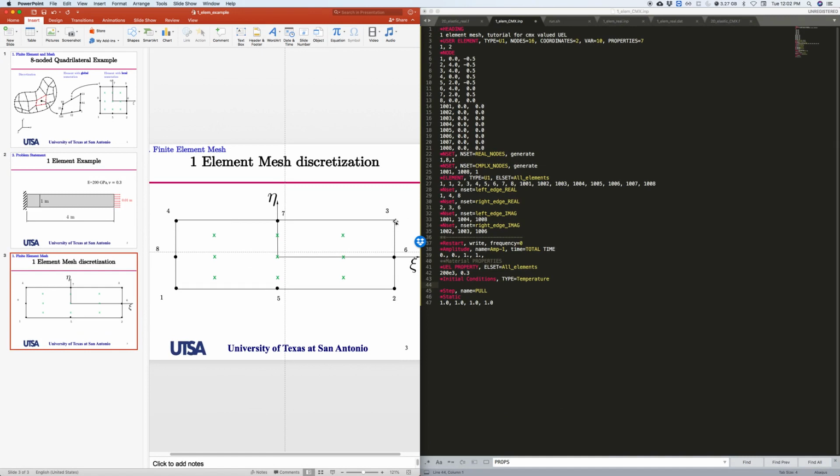So for example, I can perturb those nodes in the positive horizontal direction, to see what happens if I have a longer beam, right? So if I take those nodes and I apply a nodal perturbation over there, I'm just saying that those nodes are gonna be longer, right? So it's like, hey, what happens if my beam is longer?